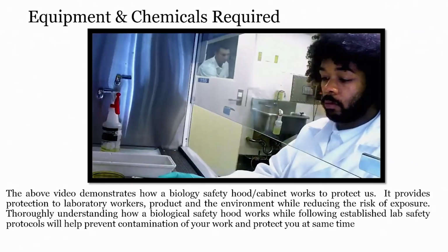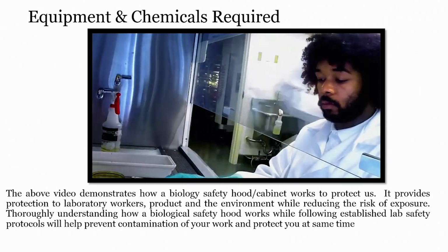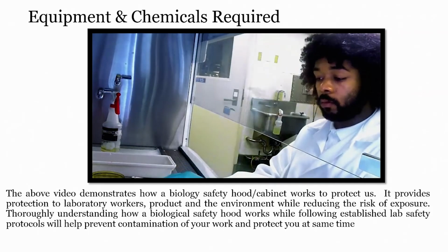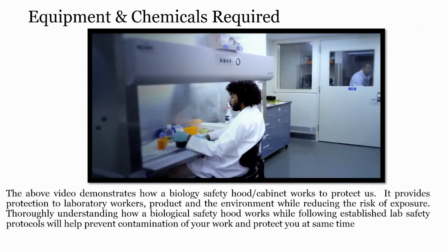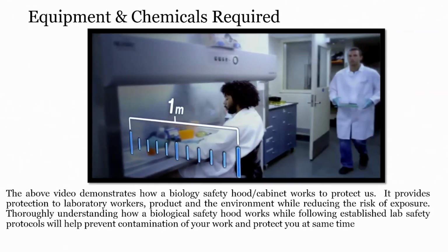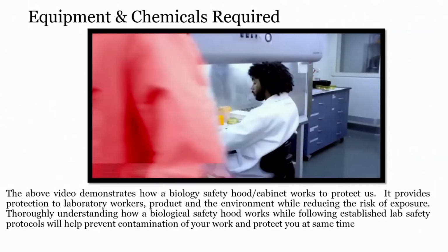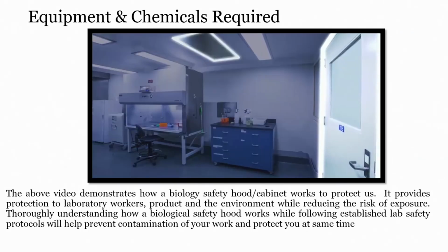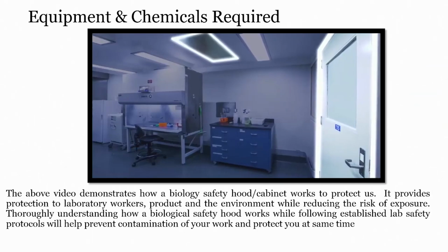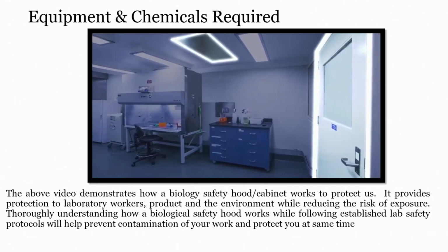Too much foot traffic can cause problems as well and should be kept at a minimum. If pedestrians are unavoidable, keep people at least 1 meter from your BSC. And remember to check nearby doors or supply vents to determine if they disrupt the cabinet's airflow.